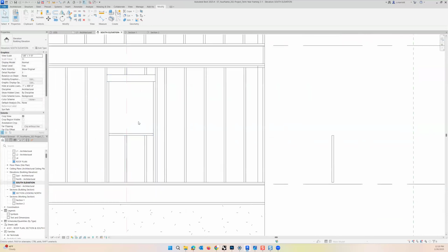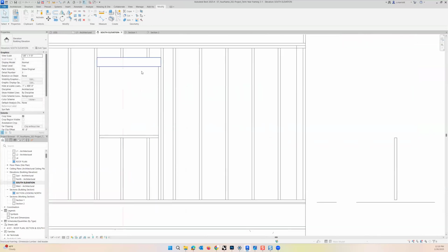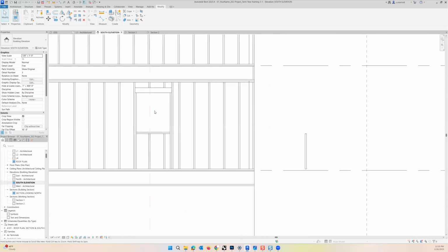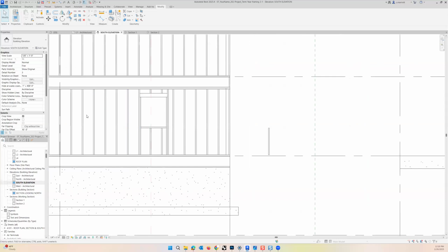Right, now, it may look a little strange that it's not symmetrical about the opening, but again, these members need to receive finishes like drywall, and also on the exterior side, some sheathing, and those follow the 4-foot module that is standard for panel materials. And so, the nailing will happen on those divisions of 48. So 16 inches on center, in some cases 24 inches on center. That's why we have that condition.